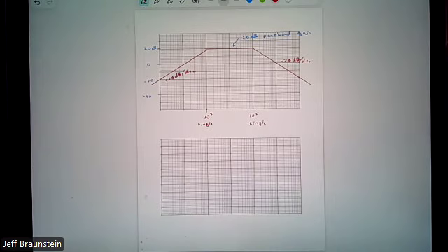But 1 over RC will give us the cutoff. For first order circuits, our pole, which is the cutoff frequency, is 1 over RC for an RC circuit. Yes, always. Doesn't matter high pass or low pass. Both 1 over RC.